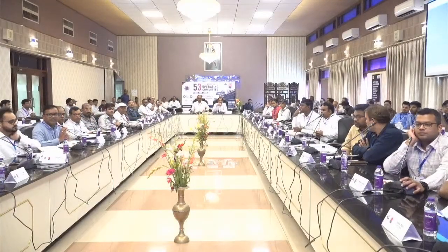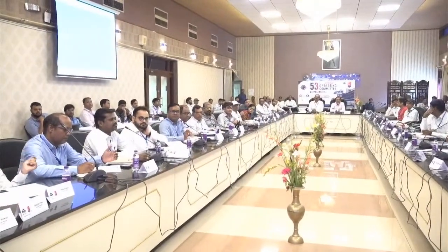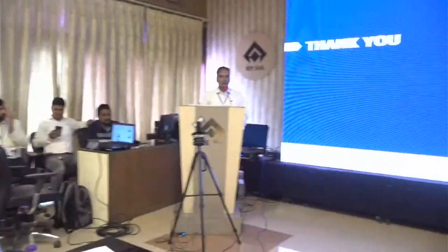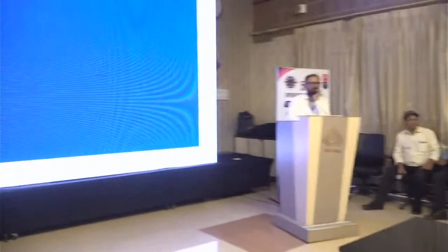So, are you measuring the vertical flue pressure? Yes, sir. Are you measuring the flue top pressure at low temperature? Yes, sir. What top pressure are you maintaining in the heating flues? In GF batteries, we are maintaining around 0.2. Are you measuring during this period?